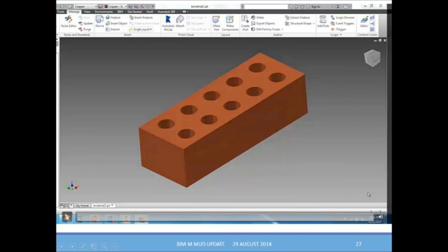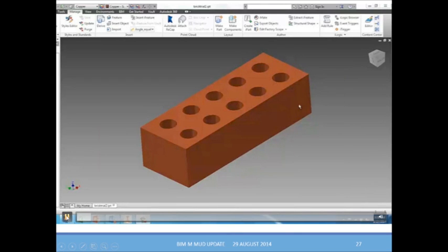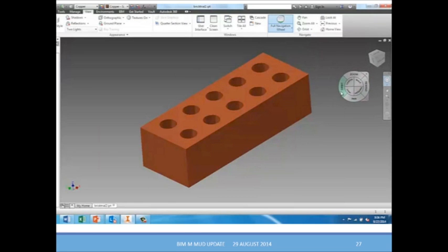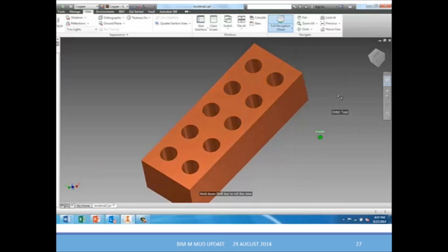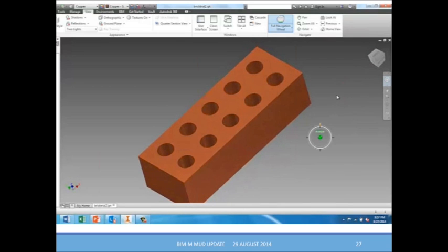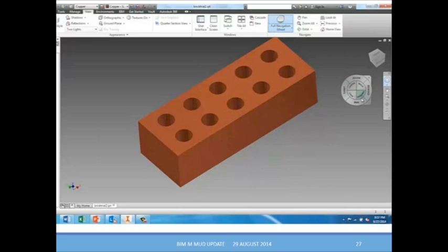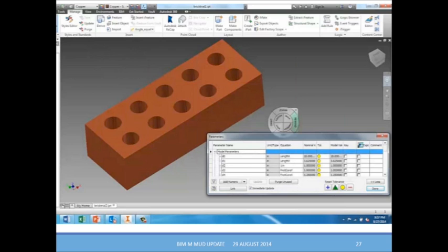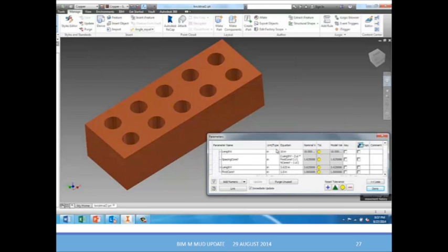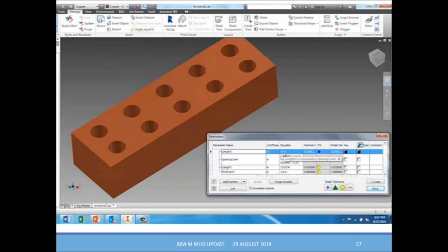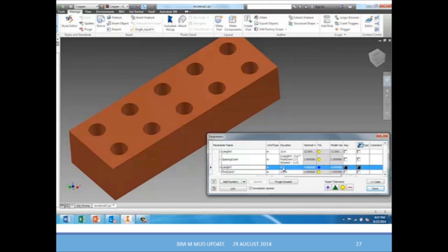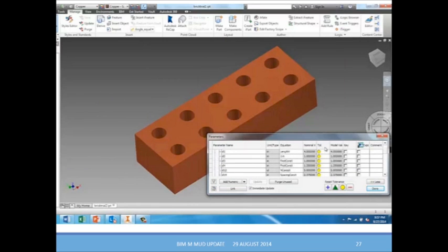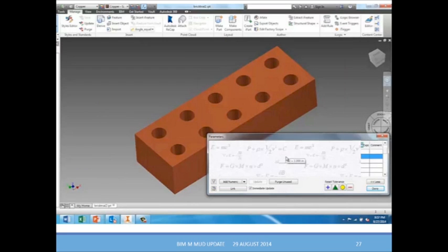If we look at a regular masonry unit, when I talk about it being described parametrically, what you can see here is a standard king brick. In this case, it's 3 5/8 by 10. So it's just a standard parametric shape. This shape was not drawn. This shape was generated from a table of attributes. And you can see parametrically, after I've generated the table from the database, I can change the attributes. I can make the brick 12 inches long, or I can make it 4 inches wide, and those drawings change automatically. So you can see the power of developing the shapes parametrically.